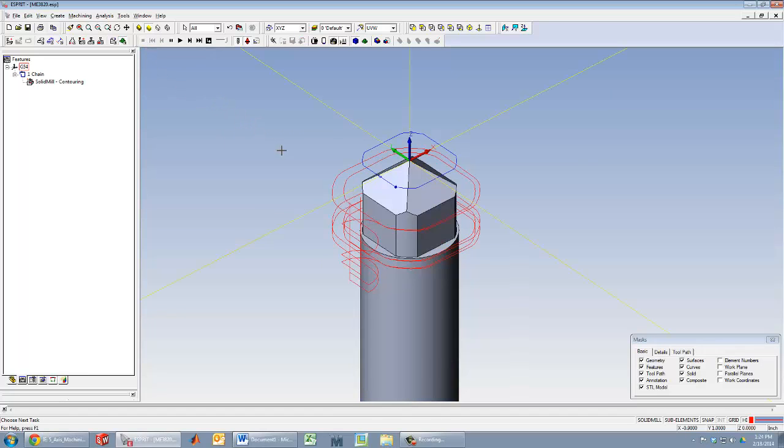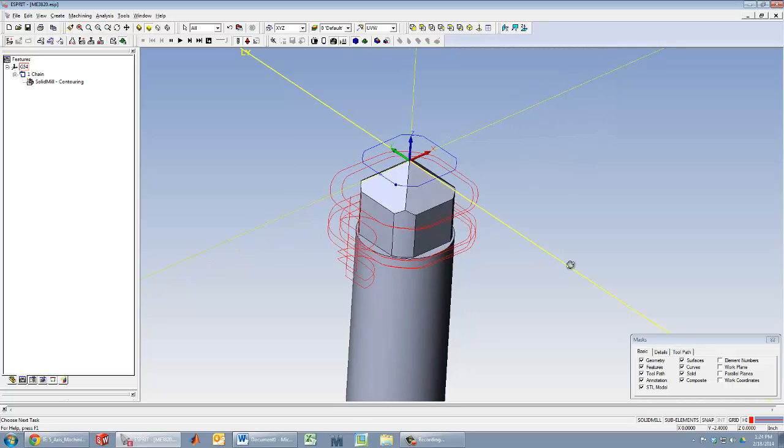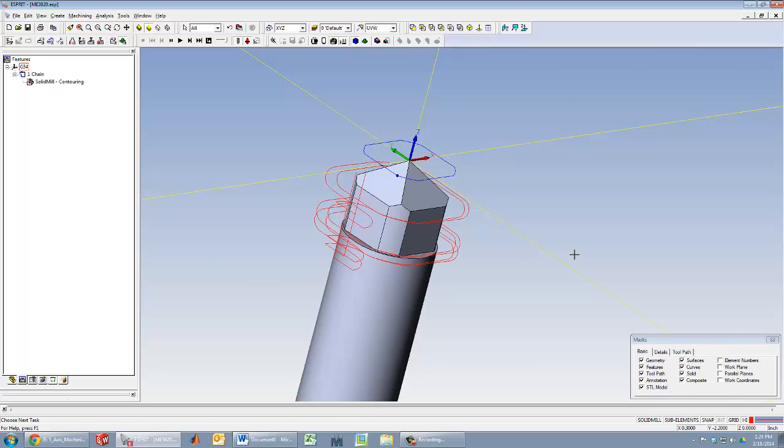So we're going to stop this. Now we can actually get into the interesting part of doing the 5-axis operations. So the first operation you're going to want to make is your 2.5 axis operation you're going to use to machine one of these faces. So the trick in doing that is going to be to control your tool orientation. Back when you only had 3 axes, the tool always came from one angle. Now you have rotary axes, the tool can come from just about any angle. And the trick is, as I just said, control that orientation.